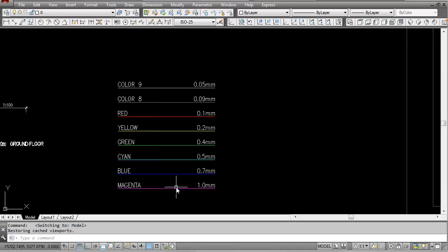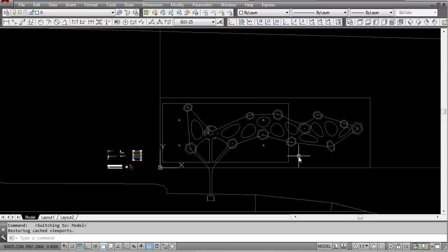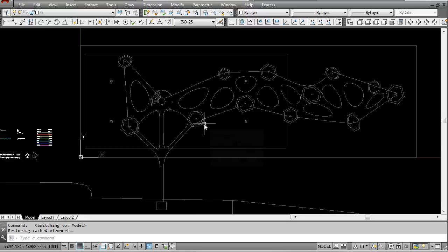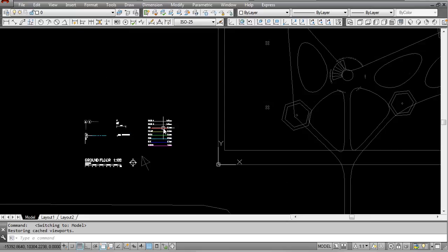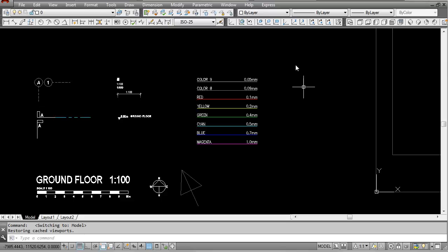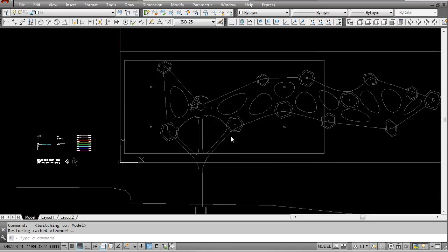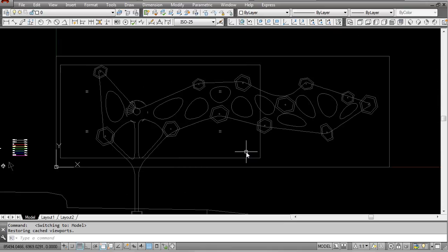If you're comfortable only using 3 colors, thick, medium, and thin, then have a CTB file with just those thicknesses. But remember as well that as soon as you work within an architectural office, you're going to have predefined templates to follow. You're most likely going to be given most of these elements that they want you to use in your plans, so that all of their plans have a certain consistency. Also remember that once it comes time to submitting your plans to authorities, those authorities are going to have certain color requirements for certain elements within your plan. So certain things are going to have to be colored red, brown, black, and so forth.